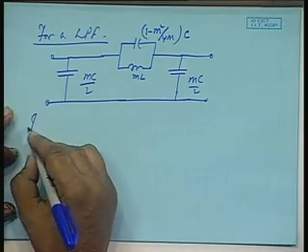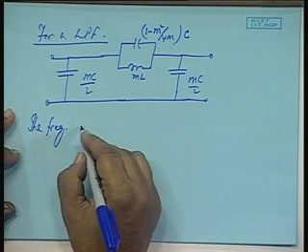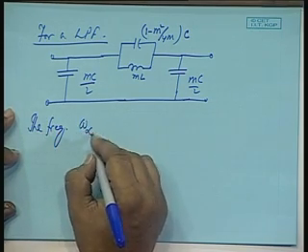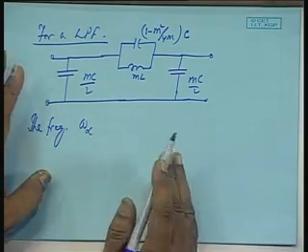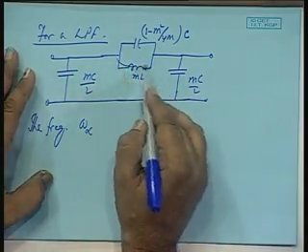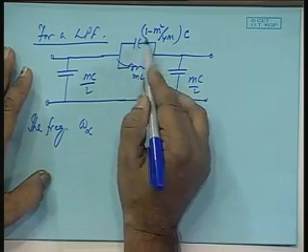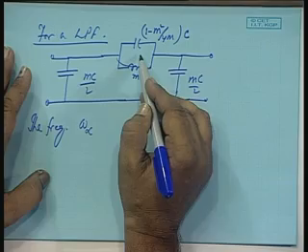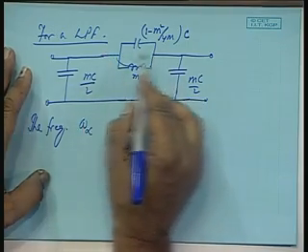The frequency omega infinity at which the attenuation will be infinity, that is alpha will be shooting up to infinity, will be corresponding to an anti-resonance frequency here. At resonance of a parallel circuit, this impedance will be infinite.